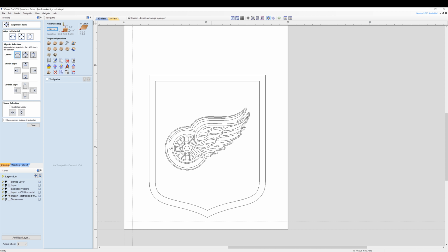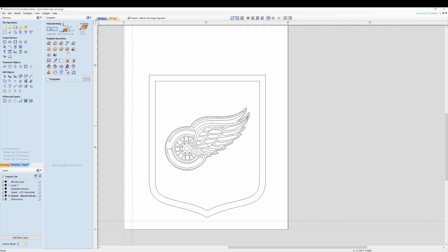And we've got a couple options as far as what we can do in this interior area. We can just use an end mill to create a pocket, just a flat plane, kind of boring. I don't want to do that. I want to have some texture there. So what I first did is use this texturing toolpath. Now, once again, I'm going to select this and press U for ungroup. That way I only select this outside here. Hold shift and select that.